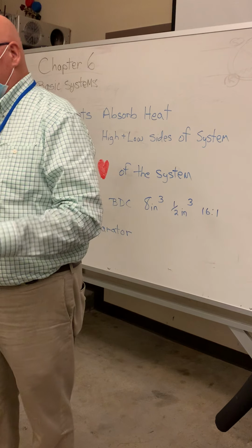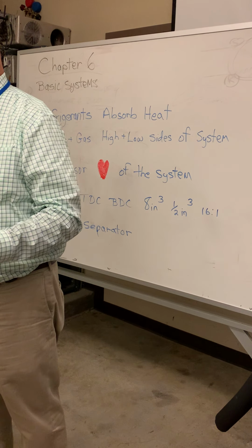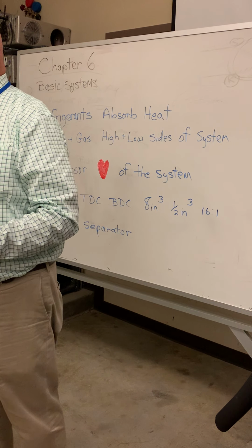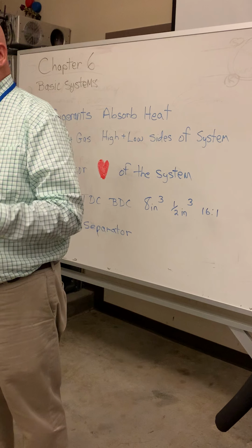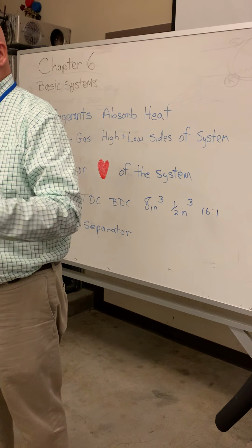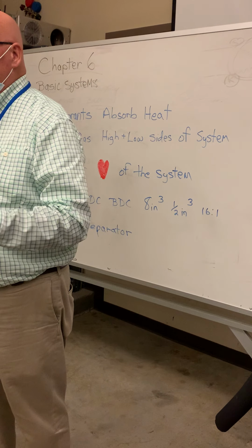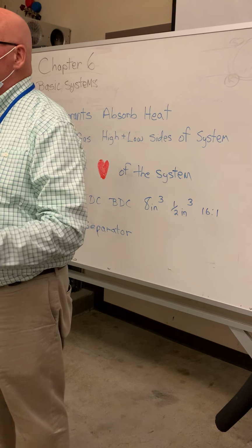One is the heat is going to go into that refrigerant vapor. The second is, if you've ever seen a steel container that holds water, and you see that it starts to sweat, that dehumidification goes on too. So every evaporator is a dehumidifier.